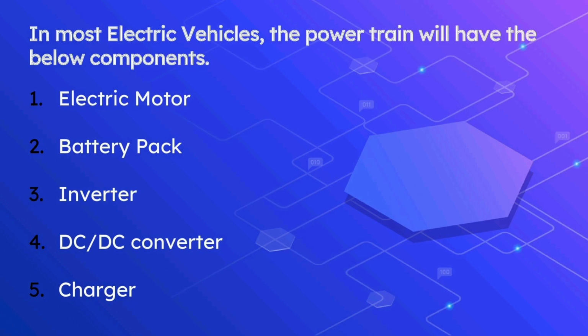This slide shows the battery technologies. Battery electrical vehicles consist of a battery connected to an electric motor through an inverter and the motor controller. The automotive batteries generally operate on DC current while the grid operates on AC. A converter is needed to transfer power to the battery.